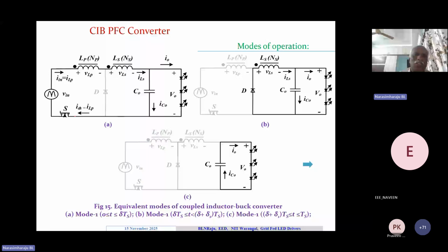The inductor resets well before every switching period in this discontinuous conduction mode. Hence the peak of the inductor current of this power factor correction converter could follow the boundary of this sinusoidal nature.